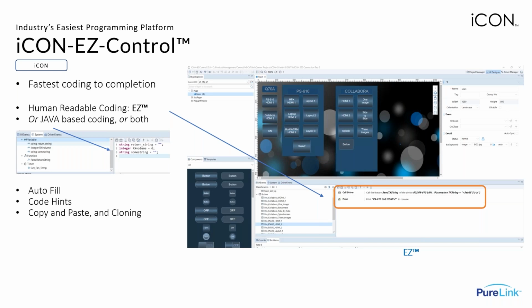You can also have password protected screens, so if you don't want somebody getting into a certain part of the user interface, they have to enter a password. You can have hidden buttons that open pages that you don't want somebody necessarily knowing are there. So you have everything you need to navigate pages.